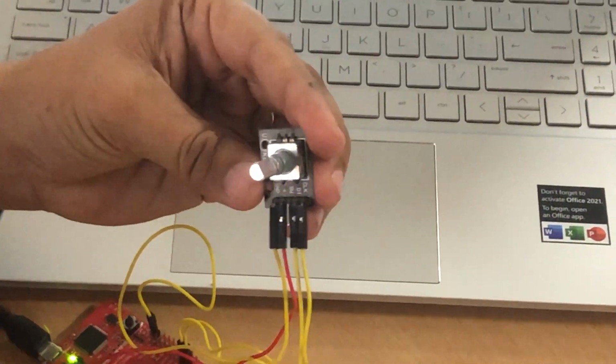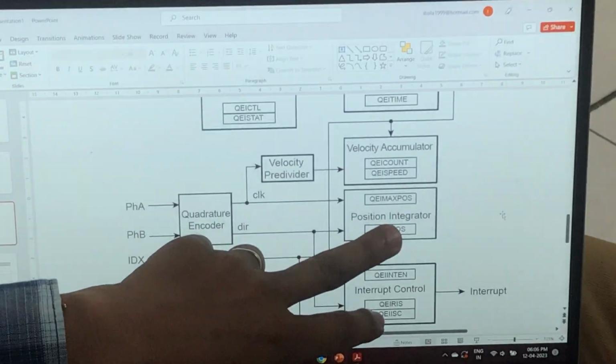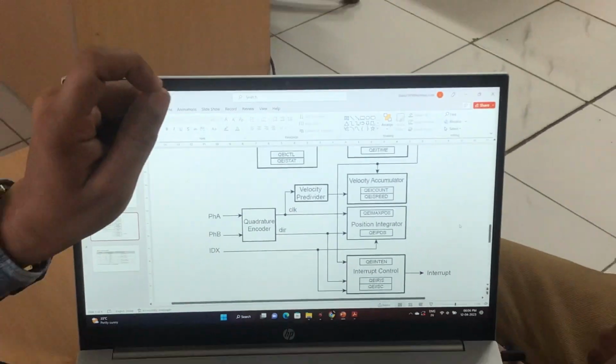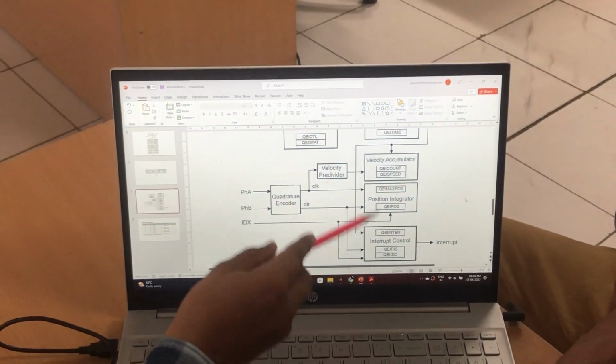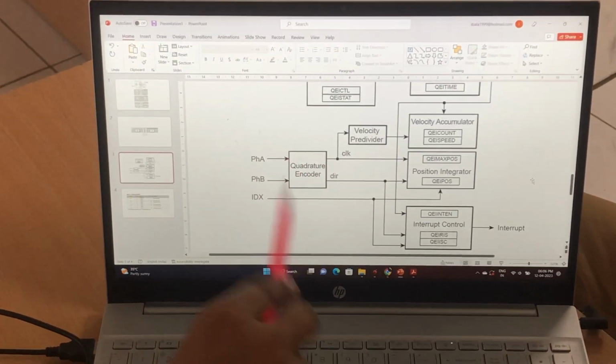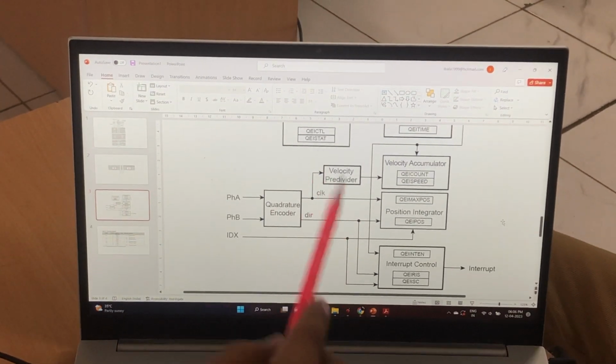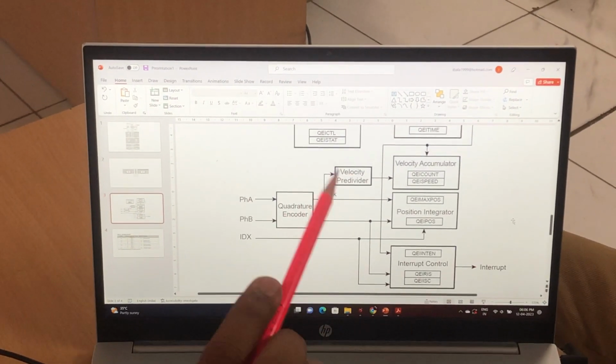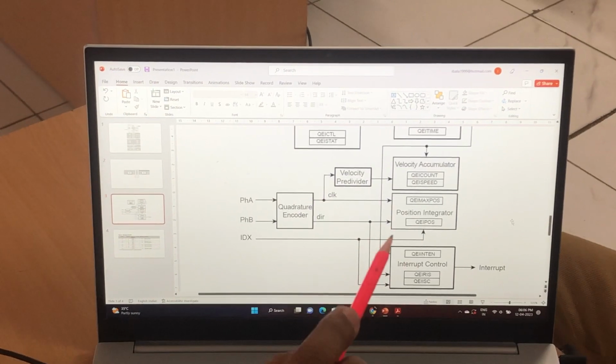The center pin can be connected to the index pin, so that index can come as an input here, which is nothing but the 0 point. Fixing the 0th point is done by the index register. If you go on like this, there is a possibility for us to make a wonderful closed loop control system which can be applicable for any DC motor based applications.